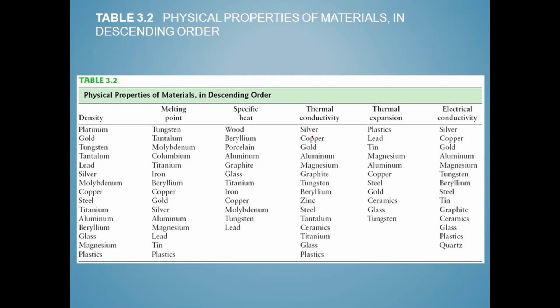You can see also thermal conductivity. The good thing for plastic is that it has low thermal conductivity, and this is a property that is required and appreciated for many applications. For many applications, like housing and buildings, we are not looking for a high thermal conductivity. Opposite, we are looking for low thermal conductivity.